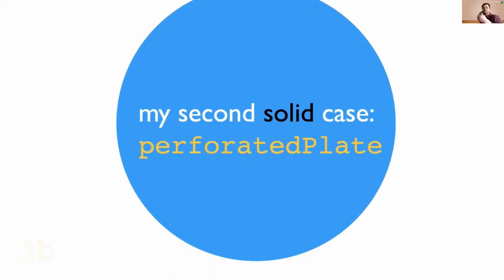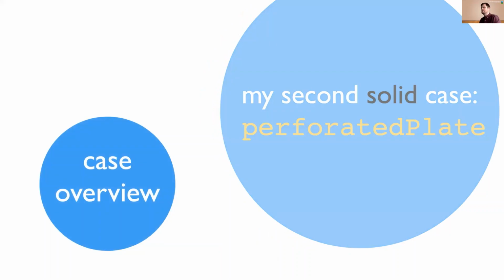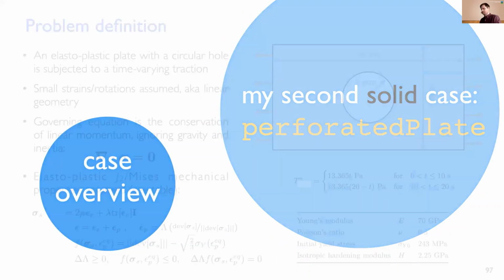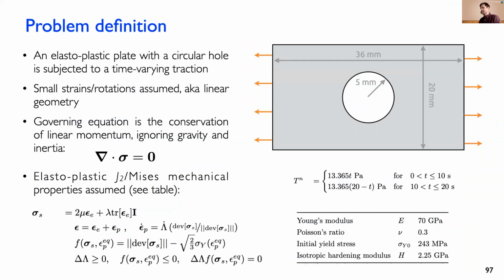As we go through this, I'll jump in between the terminal and my slides. So this is a pretty chock-a-block slide, but this is basically the problem definition. So the problem is we have a 2D plate which has a hole in it. In solid mechanics, plates with holes often come up as benchmark or classical test cases because they're simple, but they're interesting. So it's a plate with a hole, but the difference from the classical problem is we have an elastoplastic material.